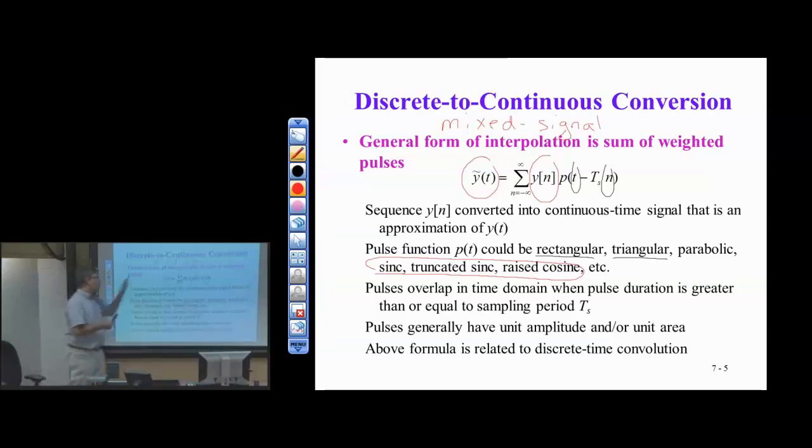So this is the discrete time to continuous time step. It is true that we want to reduce the amount of artificial frequencies at or above half the sampling rate, but we're going to have an analog low pass filter to clean that up. This is a reconstruction step from discrete time to continuous time. So why low pass, as opposed to high pass? You're partially right that we don't want to introduce too many high frequency artifacts. That's true. But why else low pass?